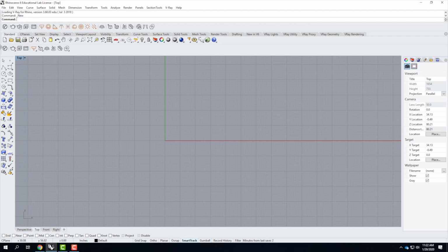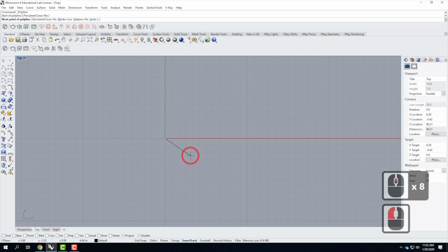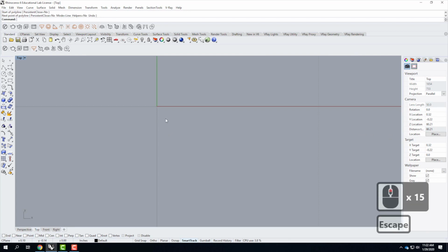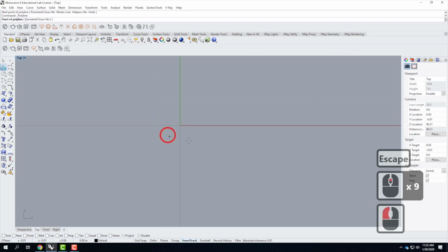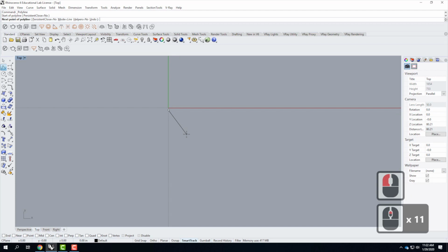So I'm going to start using the Polyline tool, which is the next tool below the arrow tool. And when I click on that Polyline tool, I'm going to come over and I'm going to start to draw. The reason those coordinate systems are important is because even if I think, oh, I'm really good, I'm going to zoom in and I'm going to pick right at that origin point, yep, that's on it. As soon as I zoom in a little bit more, I'll see, well, wait a minute, it's not really at the origin. If I were to zoom in a little bit further and do it again, okay, this time I'm going to be really good and I'm going to be on that point. Yeah, that's it. Now when I zoom in, guess what? It's still not there. So no matter how much you zoom in, you're always going to be off.